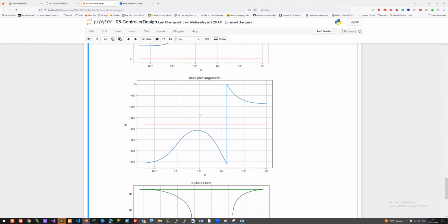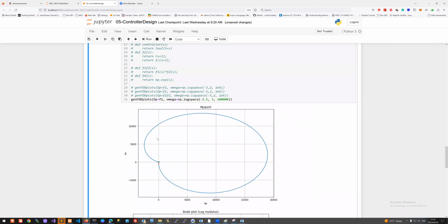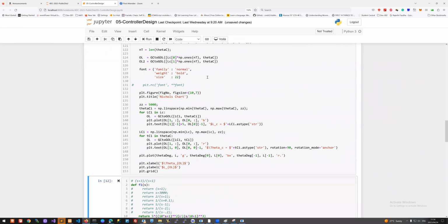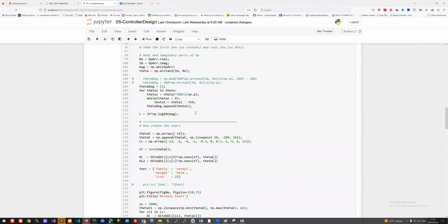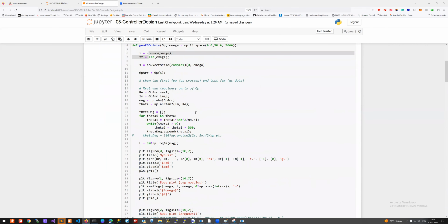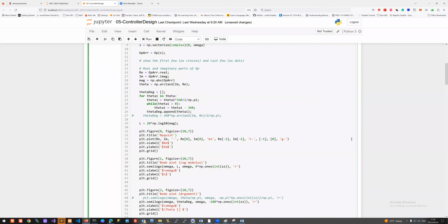You'll see a couple other things here as well. Number one, the Nyquist plot. The Nyquist plot is nothing but G of i omega, just the real part and imaginary part. So it's just the complex plane. You'll hear this term Nyquist plot. That just directly tells us about that. And in fact, it's hard to tell. This is the most direct way to check for that minus 1, 0. But it's a bit harder to see when the values are very large. So let's do a zoomed in version of this.